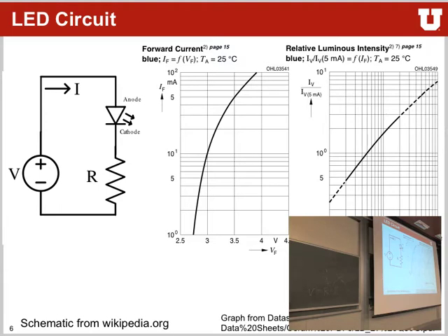Go the other way around. So you have an I/O that goes resistor, LED, and then up to VCC. What happens is that this I/O line down here, if it's high, it's at VCC. So then this line here is at VCC, so we have VCC, VCC, there's no current flowing through it. When you pull this line down to ground, current will flow through this, sinking into the microcontroller. And usually microcontrollers are better at sinking current than providing current.